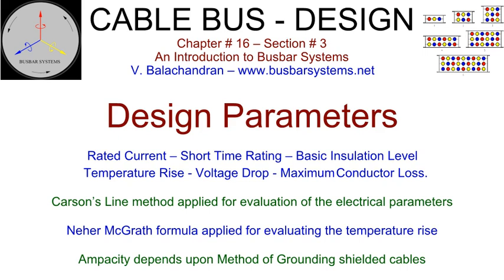However, if the shield is connected to earth at both ends, then the circulating currents will flow in the opposite direction. If the shield cross-section is not adequate to carry the same current continuously, failure could occur due to overheating. It is recommended to earth the shield only at one end while performing the short circuit test on a medium